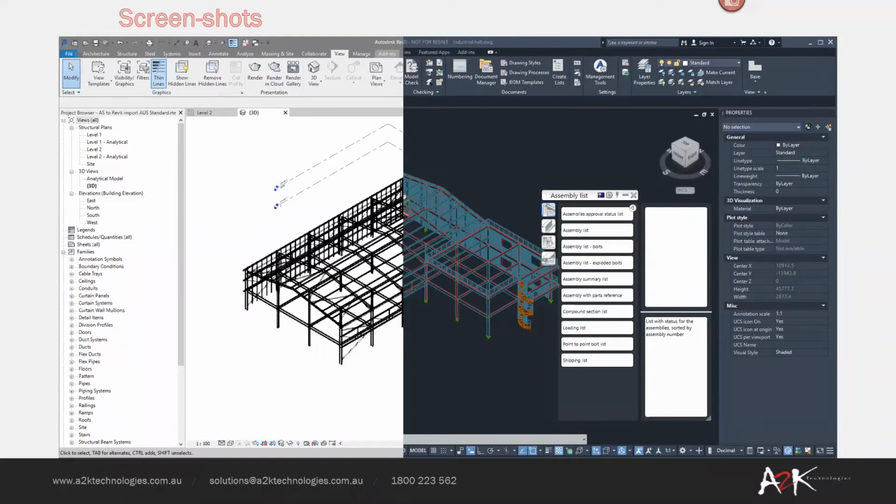Once it's exported into that SMLX format and then imported into Advanced Steel, you can utilize all the tools in Advanced Steel to add your connections, cross bracing, base plates, handrails, and so on. Once all those details have been incorporated into the model, you can use those 2 clicks to generate each of your assembly, fabrication, and erection drawings that will make that full set of steel shop drawings. You can get your bill of materials out and then coordinate all that through your Advanced Steel document manager.